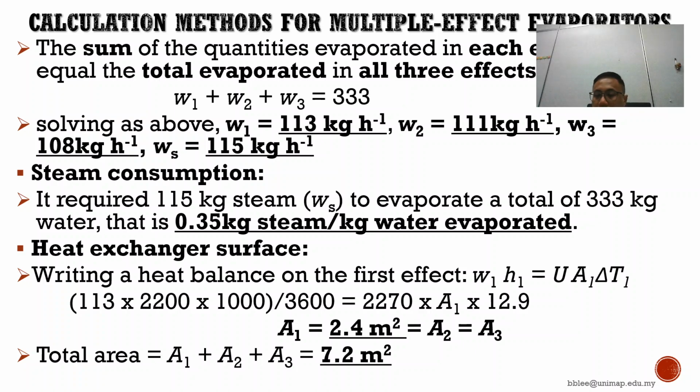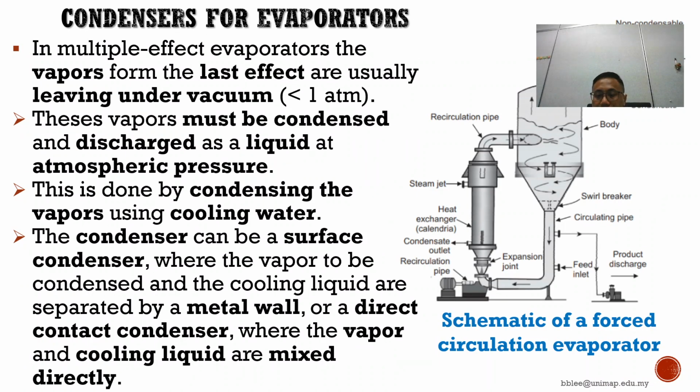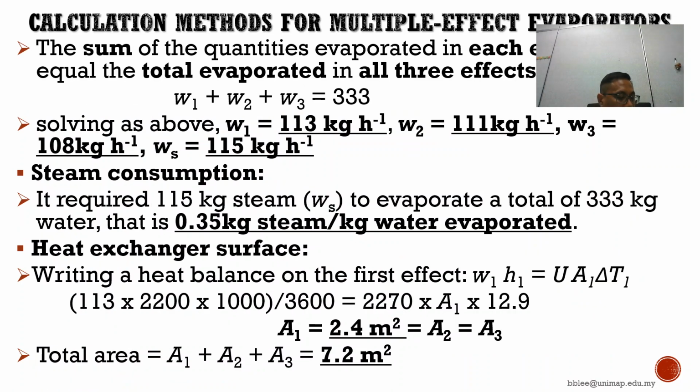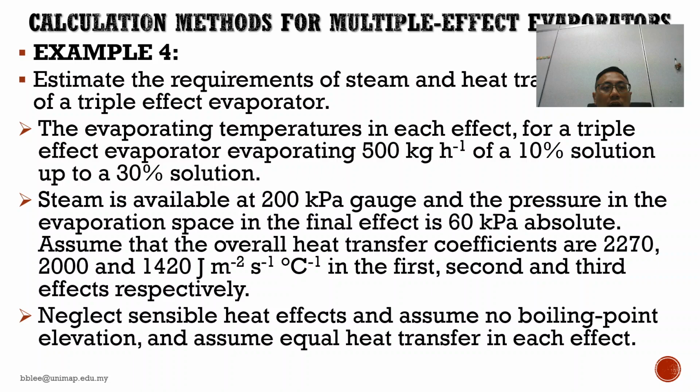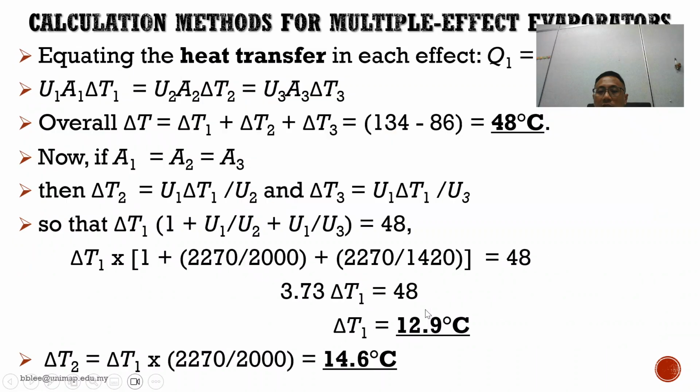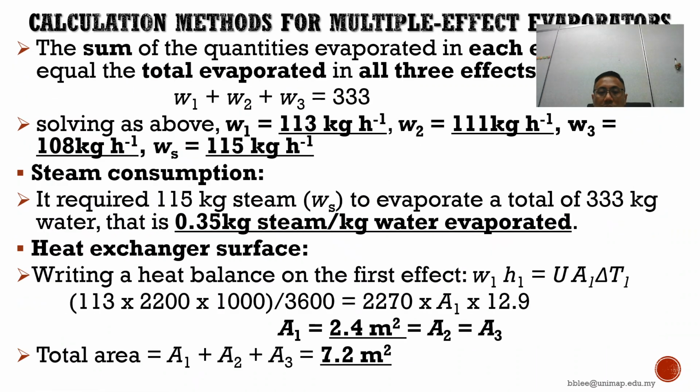Then we solve the problem. Assume no boiling point elevation. Assume no steam is available. Estimate the required steam and heat transfer surface area.